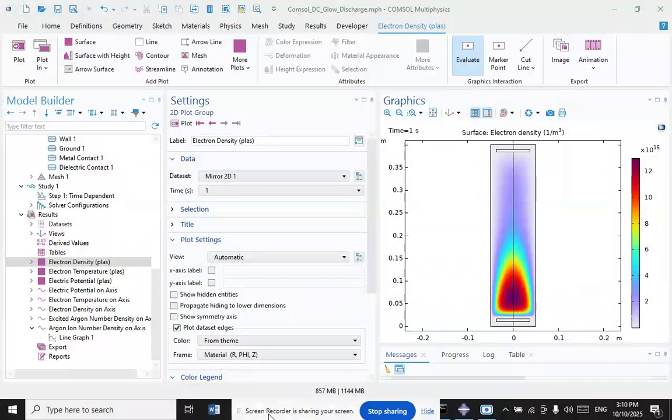Atmospheric pressure glow discharge of pure nitrogen, nitrogen-hydrogen, or nitrogen-ammonia mixtures for surface modification of polyethylene and polypropylene were reported to increase their surface energy with only 10% hydrophobic recovery.